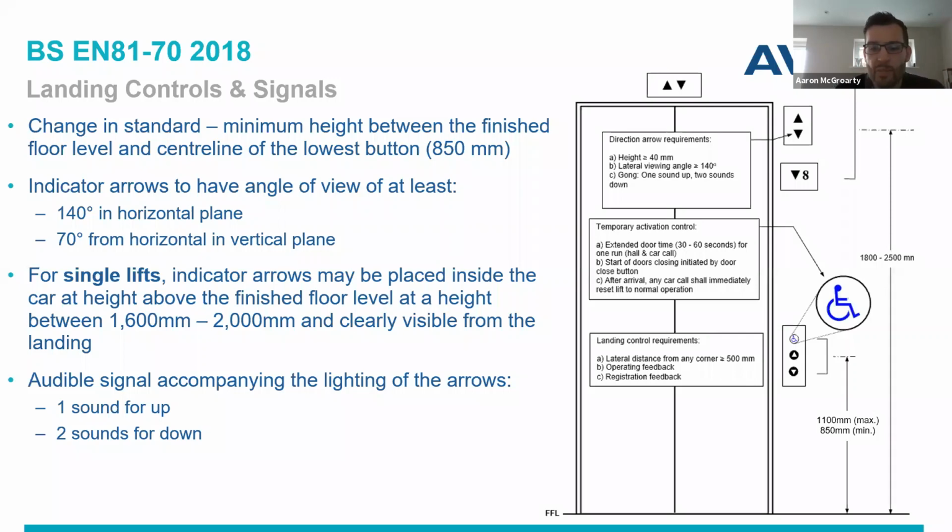When a car call has been made, the selected floor, direction of travel and allocated lift shall be confirmed with a visible signal. You'll all be used to seeing these hall lanterns that light up when the floor selection has been chosen and the elevator has been designated. The visible signal should be placed near the input device, so usually the LOP for the destination call.